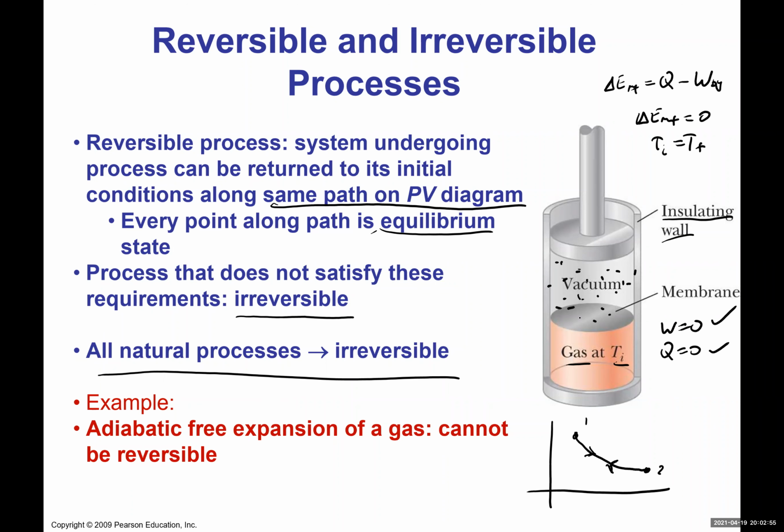So the system changes because compression increases the temperature of the gas: as you're compressing, the pressure changes because the volume changes, and then the temperature changes, right? By doing that work of pushing the piston inward, we are increasing the temperature, which should make sense, right? Whenever you have a compression, the temperature increases. Now, one thing we can do here is lower the temperature by allowing the gas to come into contact with some external energy reservoir. For example, if we put this in some kind of cold bath and allow the energy to move from our system to the surroundings, right?